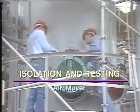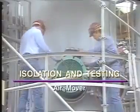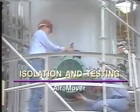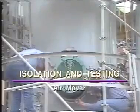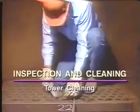After the column is purged and tested for hydrocarbons, one of the manways is opened and an air mover is turned on. The air mover can be a fan or an air eductor like the one shown here. In the event that any hydrocarbon vapors are released during the cleaning of the tower, the air mover will sweep these vapors out of the tower. Cleaning of the tower should be thorough and complete.